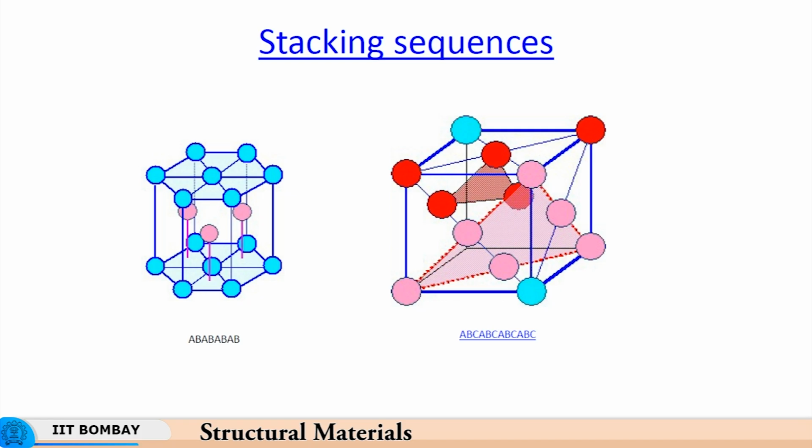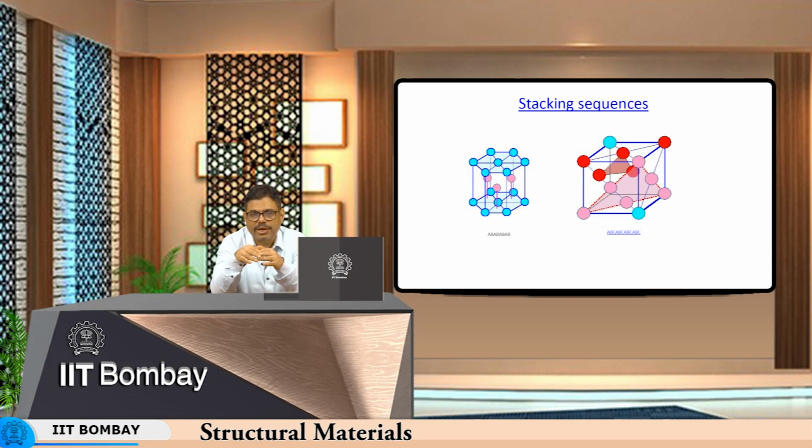We will continue with the explanations a little later, but it is enough for now to remember that the stacking sequences can get disrupted and it can affect the deformation in the later part, when the material has work hardened a lot and starts behaving softer, as a result of either dynamic recovery taking place or new grains being formed by recrystallization, because of the stacking fault or stacking fault energy, as we call it.